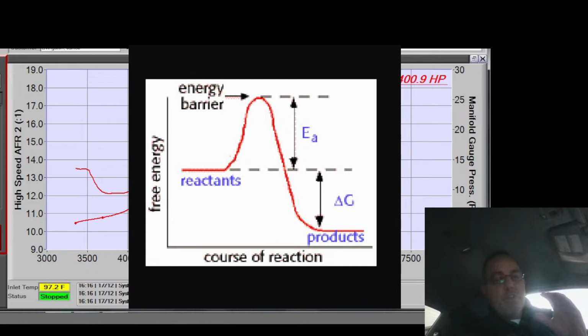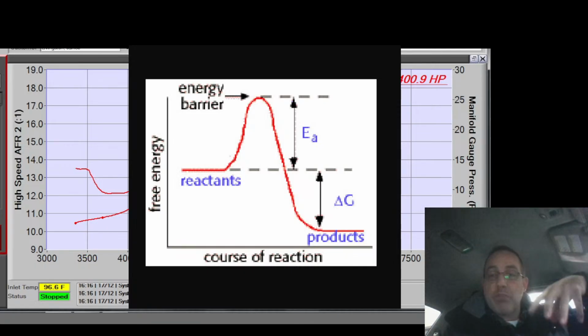Because when you start that, you saw electrodes in the way, and so like if I show the plug as if it's like this, right? But really it's in the cylinder like this, right? So when I start burning fuel, it's shielded by the ground strap. That electrode shields the kernel, so it's going to start burning in this direction, and it's going to go out and then up, right? Some chambers, though, are set up in a way where they pull that electrode down so that flame kernel goes up into the chamber.